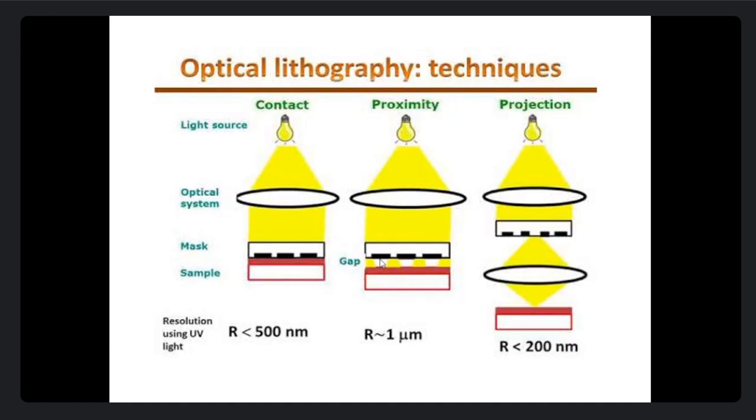But anyway, that is a possibility I'm talking about. So you have to keep that in mind also. Automatically there is some kind of tilt of the mask with respect to the wafer, or both. Then automatically the gap will vary.